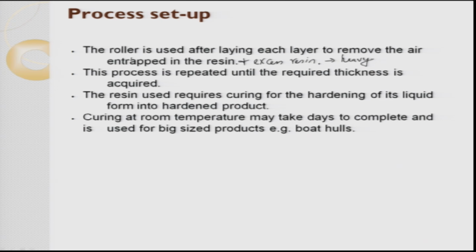So, they will always make sure that the air gap is removed so that you get a better performance, and the excess resin is removed such that the weight is reduced. The process is repeated until you get the required thickness. The resin used requires curing for the hardening of its liquid to form into a hardened product.